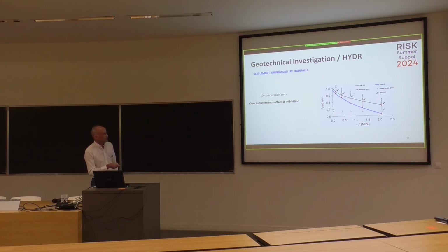So these tests were done on a calcareous sand. Okay? And if we do the same with glass beads, we are insensitive to grain crushing. There is no effect of the water. So this effect, the sudden collapse of the specimen, is due to the interaction between the water and the particle because of breakage.